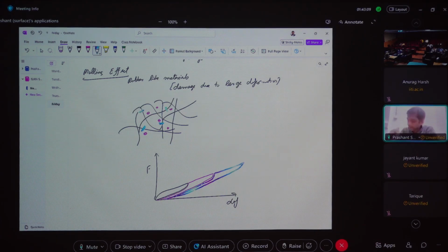So this is basically called softening. Your material has become softer and softer because of damage. So there are other more complex models to capture Mullins effect, and basically what you do is when you manufacture a new material in the lab, in the factory, you do some cyclic loading on it just to remove all the Mullins effect before it actually goes into actual production and actual product. So this Mullins effect must be accounted for whenever you have a new thing that you make in the lab.